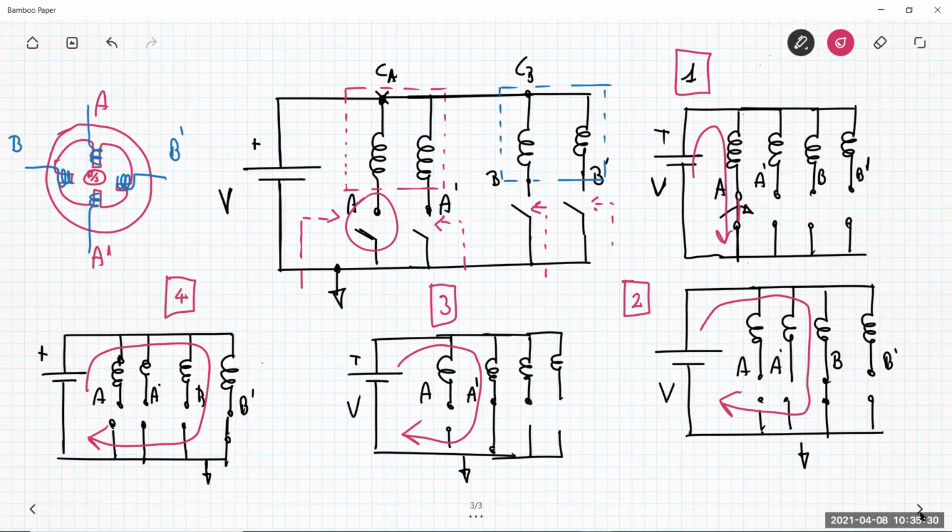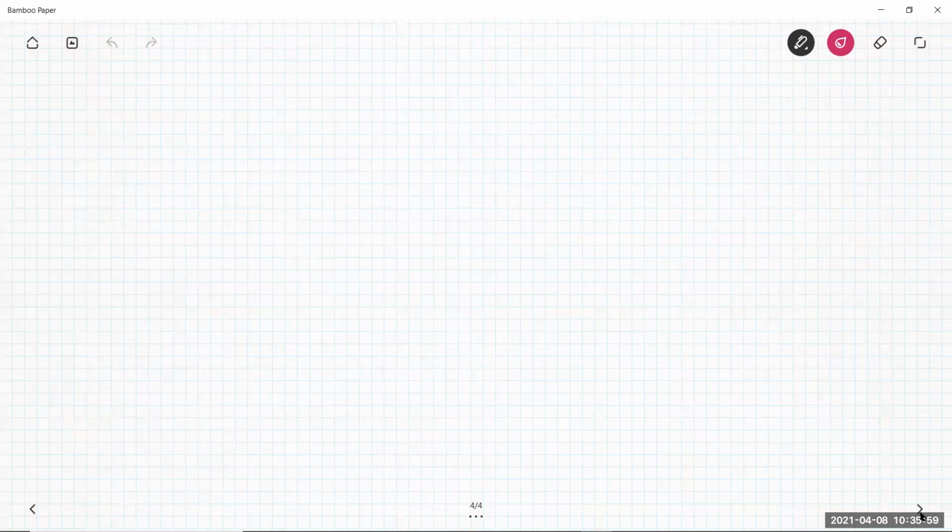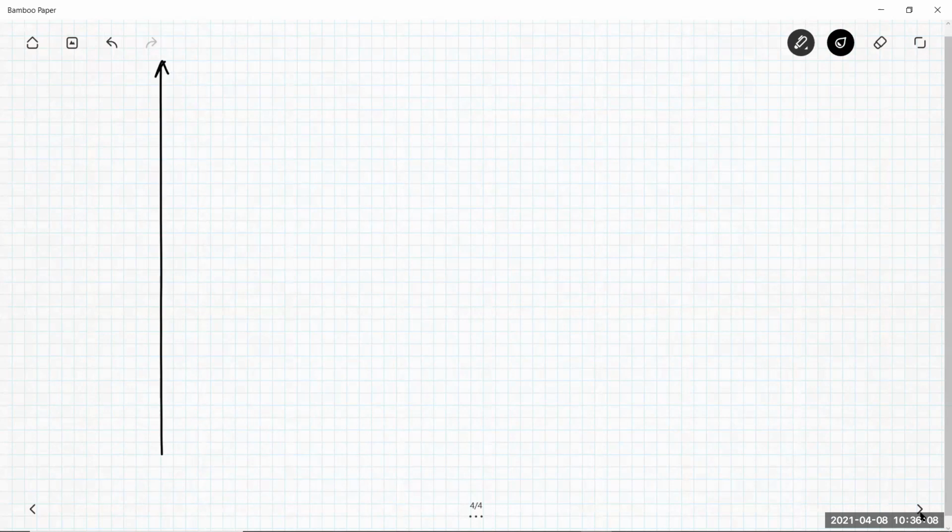Okay, for example, if the voltage VGS is less than the threshold of the MOSFET, the MOSFET is open. So at the output port, drain source, this MOSFET is like an open circuit. If you drive the MOSFET with a voltage VGS which is higher than the threshold, and you drive this MOSFET in the resistive linear operating region, you can consider this MOSFET fully conducting. So this MOSFET basically is a very small resistance between the drain and the source. You have almost a short behavior, like a closed switch. Okay, so which is the behavior of this control signal for this MOSFET, or for this generic transistor that you can employ as a switch?